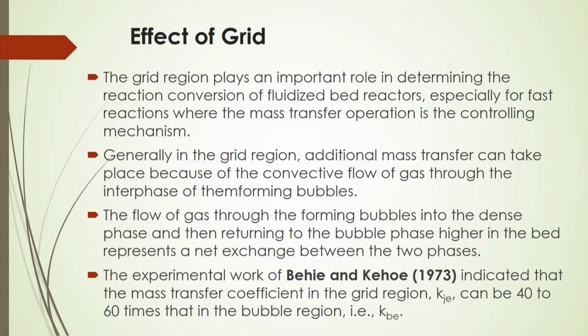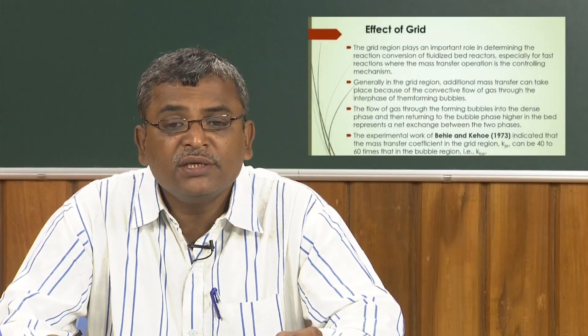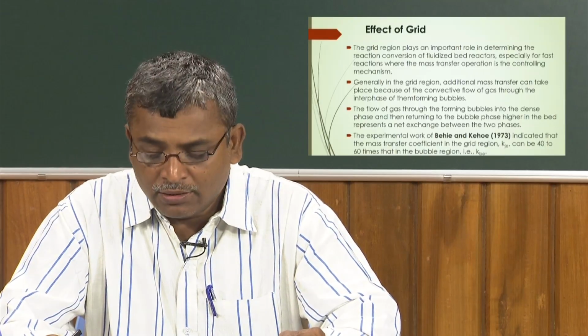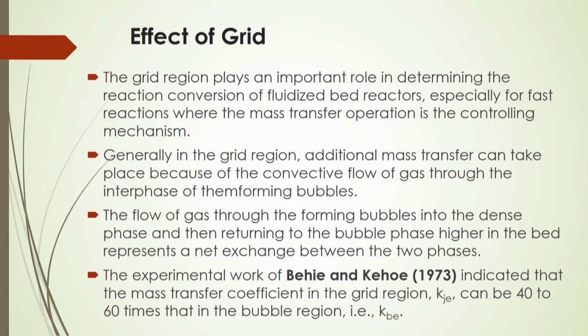Now, the experimental work of Kobayashi and colleagues, 1973, indicated that the mass transfer coefficient in the grid region can be 40 to 60 times that in the bubble region. So, this is very important: the grid region will enhance the mass transfer coefficient inside the bed.